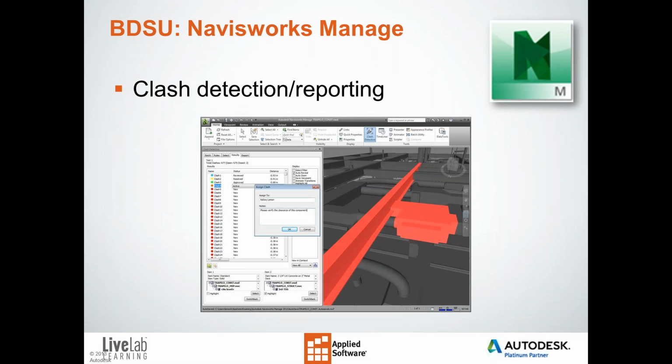Clash detection, what most people think of when they hear Navisworks Manage. The clash detection tool supports identification, management, and resolution of clashes. You can better anticipate and help reduce potential clashes and interference problems before construction, minimizing expensive delays and rework. With Navisworks Manage, I can perform clash detection tests against specific geometry to help find and resolve conflicts.